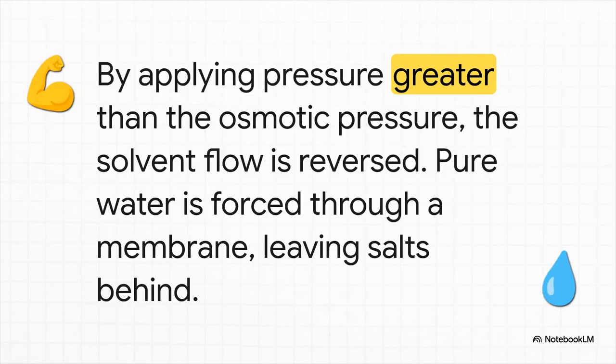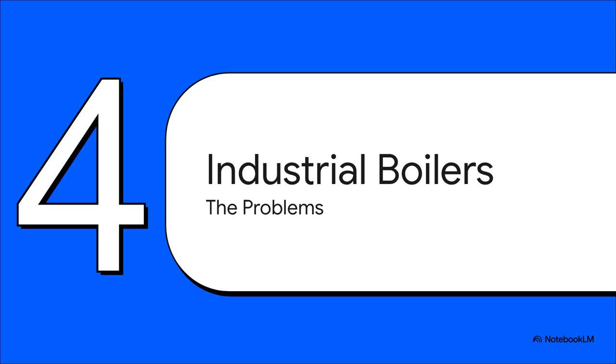So, reverse osmosis is all about fighting that natural tendency. What we do is apply a whole lot of mechanical pressure to the saltwater side, way more pressure than the natural osmotic pressure. This forces the water molecules to go the opposite way they want to. The pure water gets squeezed through the filter, leaving all the salt and other junk behind. Pretty clever, right?